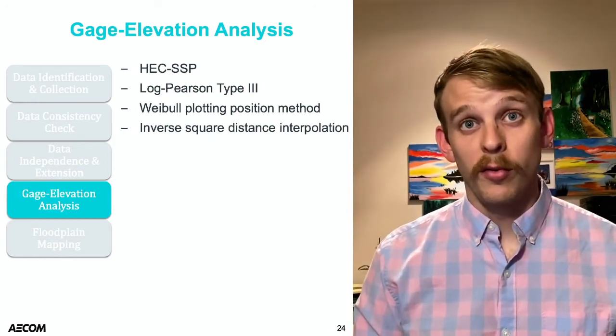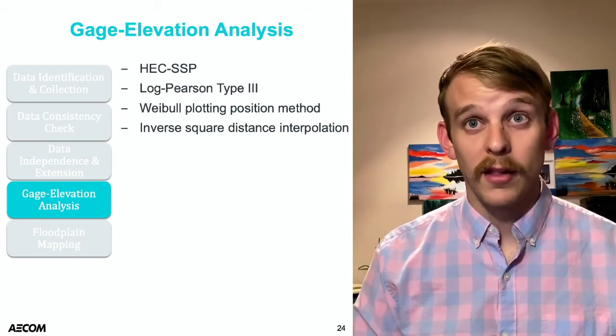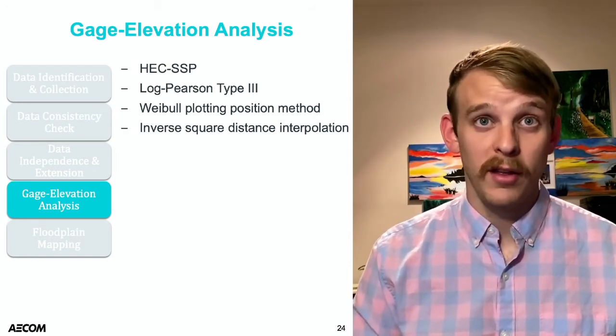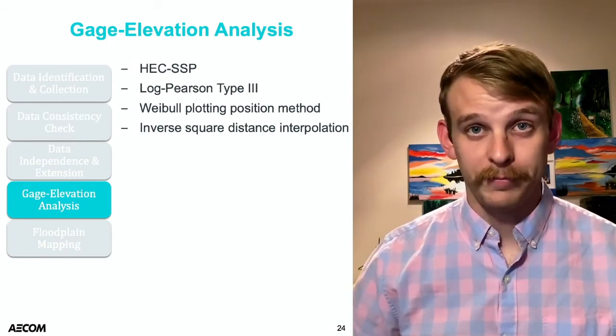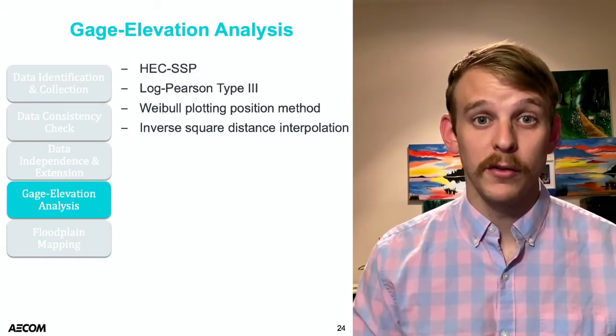This also incorporated the use of the Log-Pearson Type III analytical frequency analysis and the Weibull plotting position method, and also the inverse square distance interpolation, which calculated the spatial average frequency elevation values for Lake Champlain.